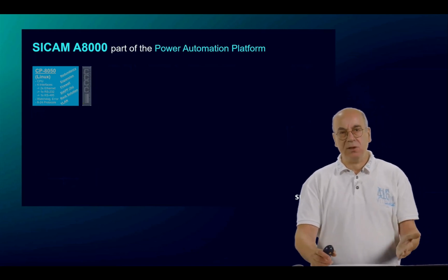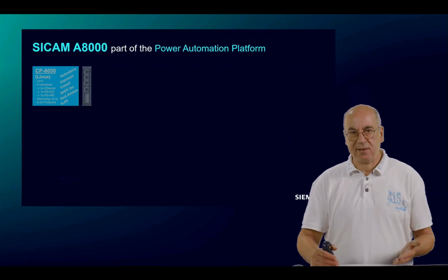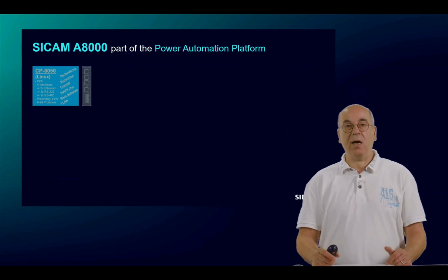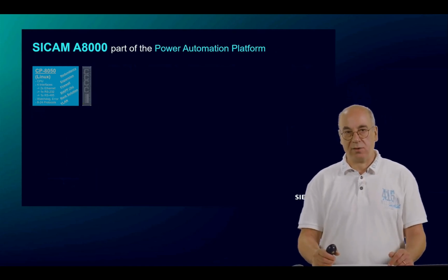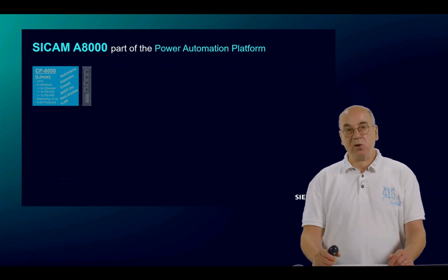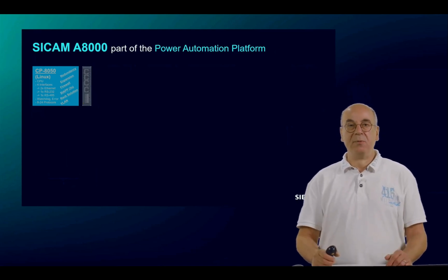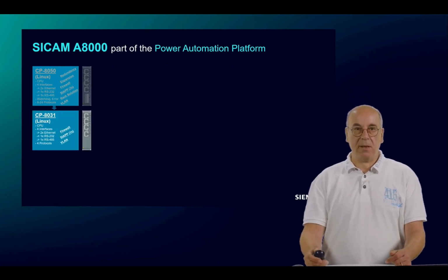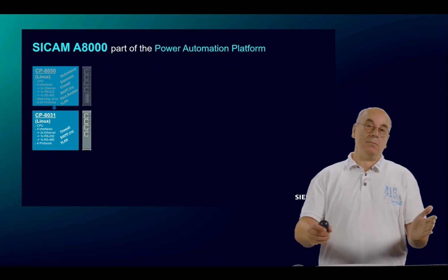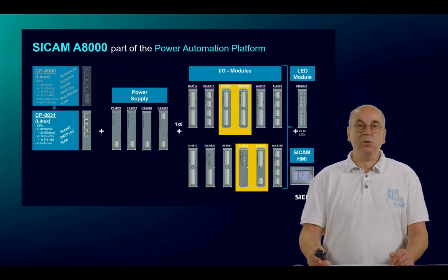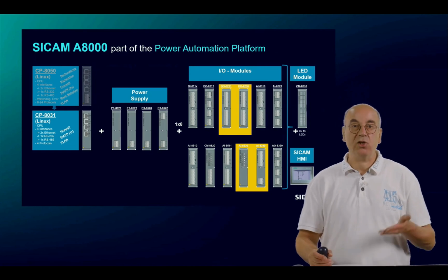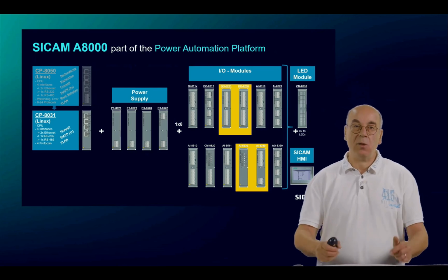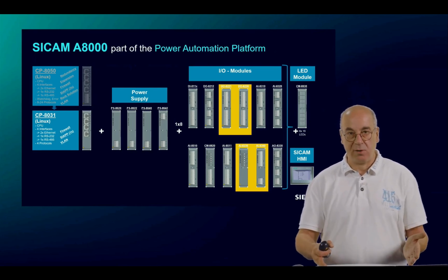And as it is not possible to equip the extended processing license on the CP8031, the rack solution is also not supported. And it's not possible to load additional protocols. And only 1 runtime container for 1 CApp application is allowed instead of the 3 the CP8050 has. It was not possible to connect additional remote I/O lines or additional communication modules. Only input-output modules in the main line and the communication interface of the CPU itself were possible.